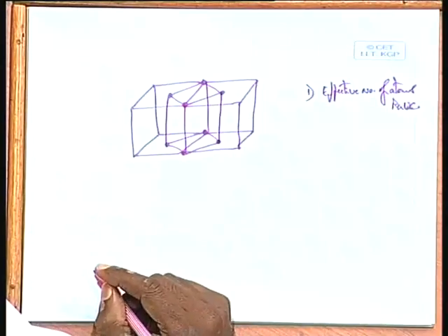Okay. Then take another possibility. So, obviously then that means base centered cubic is not possible. So, if at all there is a base centered cubic, we should call it a tetragonal. But at the same time there is a problem with this kind of an argument. The problem with this argument is, tetragonal, what is the symmetry of it with respect to cubic? Which has a higher symmetry?